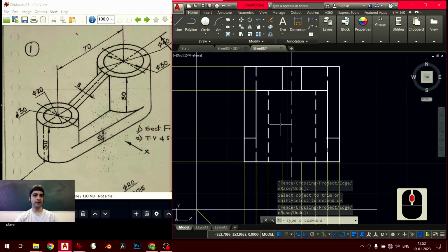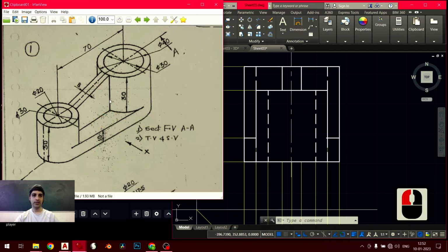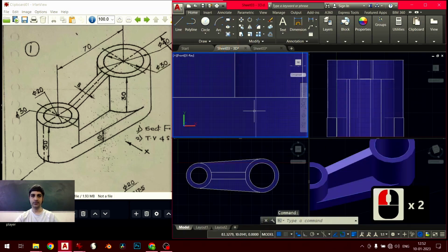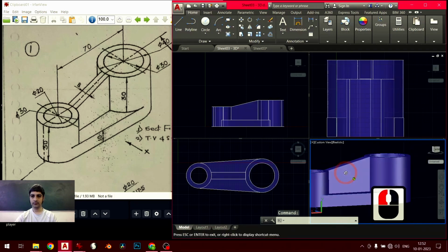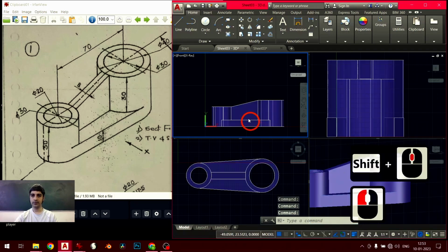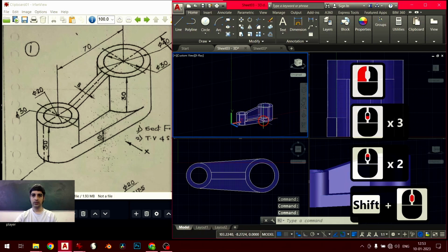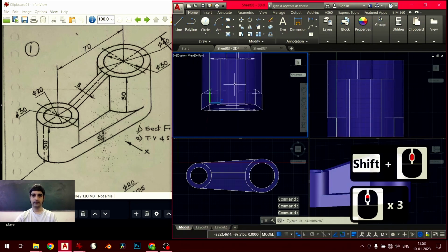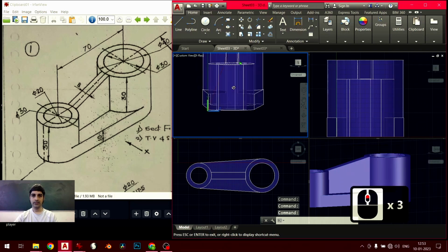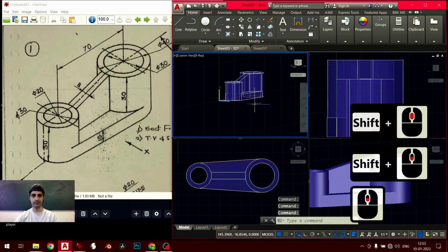Then there's hidden features that are not very obvious. So for example, this vertical edge is formed all the way from the top of the cylinder to the bottom. So there'll be a portion of it that's hidden from your view because you're looking at it from a side perspective, right? So here, or even this angle for that matter, if I just show you an X-ray view, you can see the edges formed at the back of this rib.